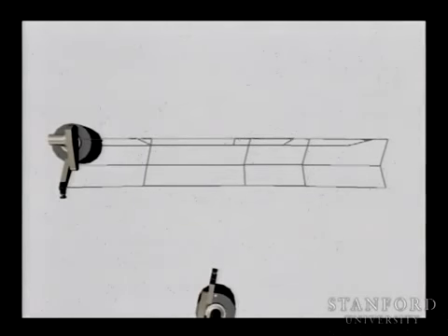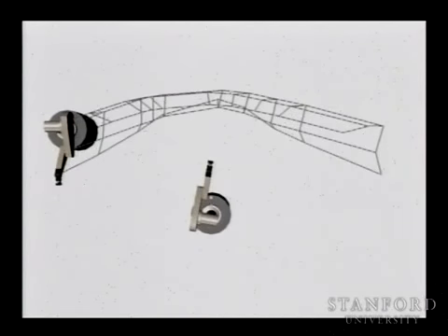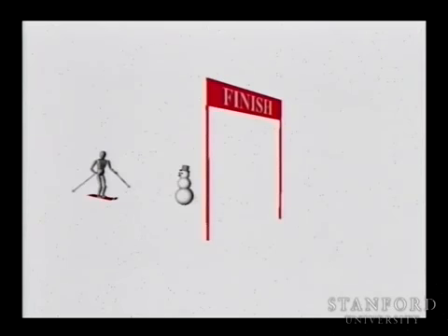So if you put two magnets north-north, they will repel. And this is exactly what is happening. We are creating artificially those forces and making the robot move away. But if you have a global plan, you need to deal with the full plan so that you will not reach a local minima. And we then apply this technique to modify all the intermediate configurations so that a robot like this would be moving to a goal position through this plan.